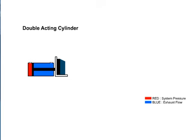These cylinders are also classified as differential cylinders because of their unequal exposed areas during extend and retract. The difference in effective area is caused by the area of the rod that reduces the piston area during retraction. Extension is slower than retraction because more fluid is required to fill the piston side of the cylinder. However, more force can be generated on extension because of greater effective area. On retraction, the same amount of pump flow will retract the cylinder faster because of the reduced volume caused by the rod. Less force, however, can be generated due to less effective area.